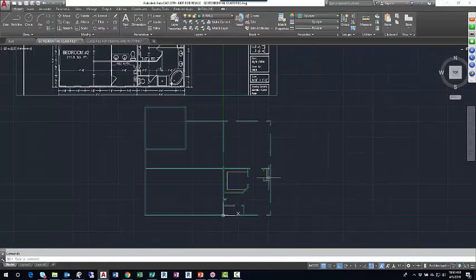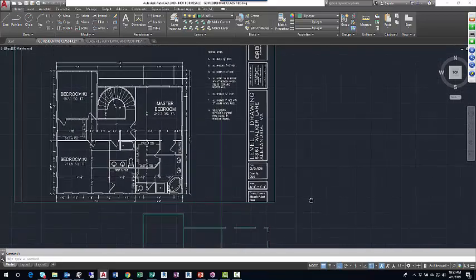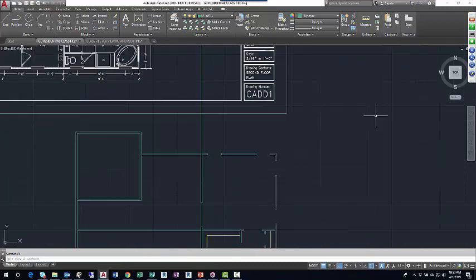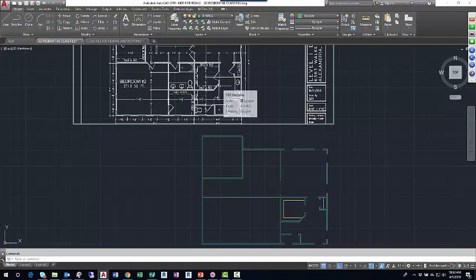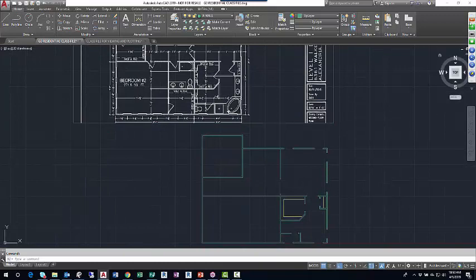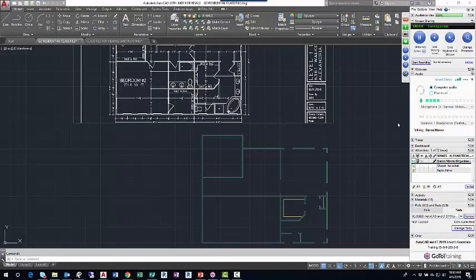So we use the attach command to attach the PDF to the drawing. We enlarged it using the scale command. These are all commands that we'll cover again. But to this point, we've just got some line work done. Polyline command we use to sort of outline the perimeter of the left side of the building, and then using the dimensions on the markup or the 11 by 17 handout, and then offset and explode and trim and so forth to sort of get where we are. So questions on anything before we get into just sort of progress forward, move forward with the exercise?